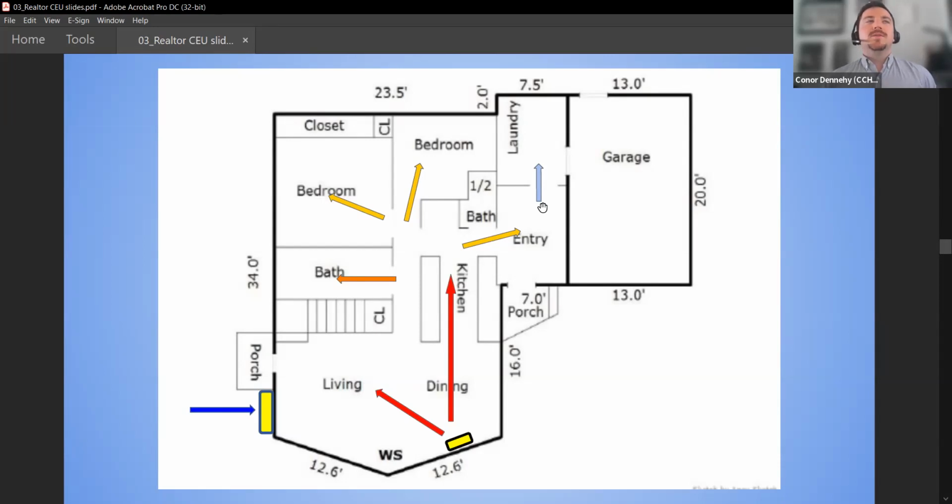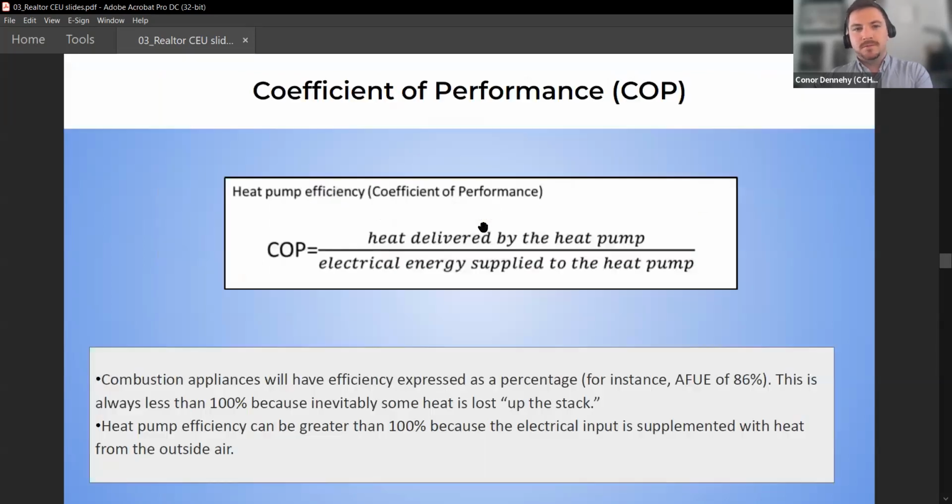The thing to keep in mind is people see price tags for ductless mini splits and they're like, wow, that's incredibly cheap. I can get one for $2,000 because I saw that online. And then once you actually start to think about the install, what's needed in the house and all the accessories, suddenly if you're installing 3 or 4 mini splits in a house, you're getting to a price point that's almost competitive with the conventional system. So what have you really gained out of the ductless scenario? It's just something to think about, and whether the house is actually a good fit for it.